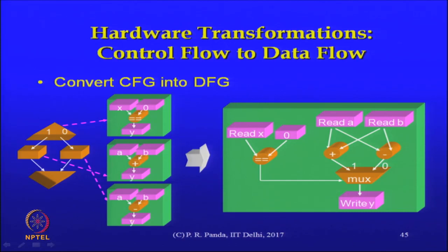So, that is what the original CDFG was. What we are saying is this is so simple that why do not I just create that data path element, that mux there. Right now, even though we haven't gone to the later resource allocation and sharing kind of steps yet. And I just translate this into a data flow graph by essentially throwing out the if statement completely, but transforming that into a mux component or a mux functionality. So, it actually becomes a node in the data flow graph with the functionality being that of a mux.